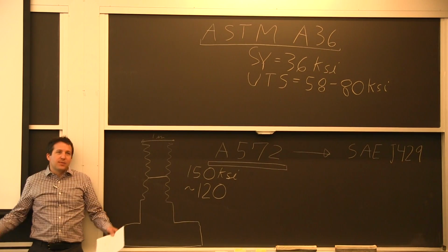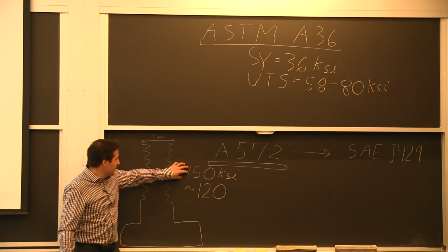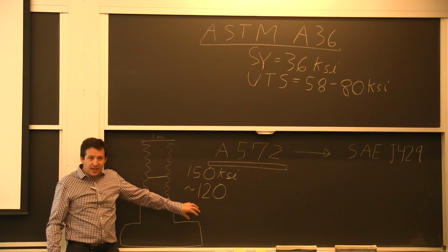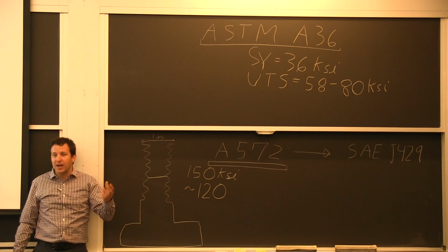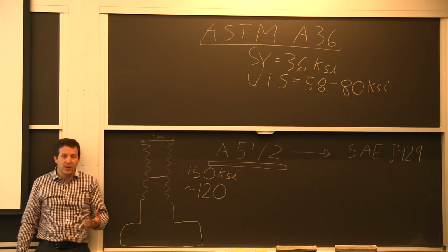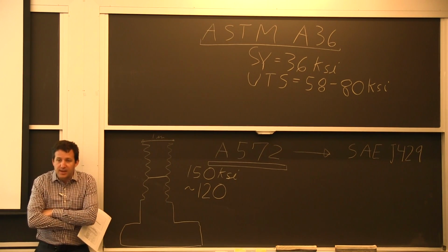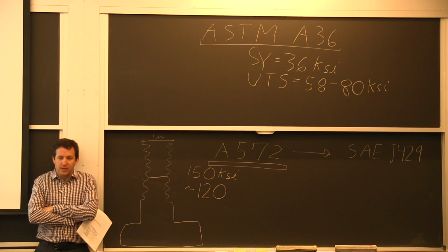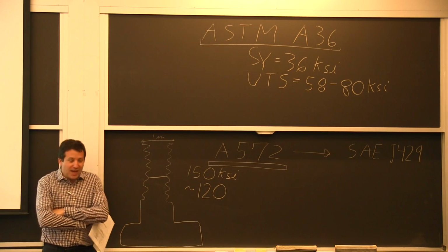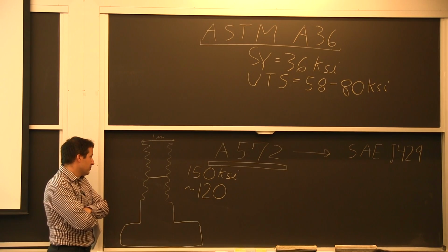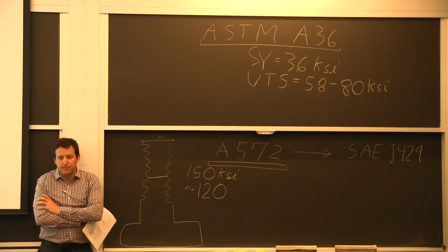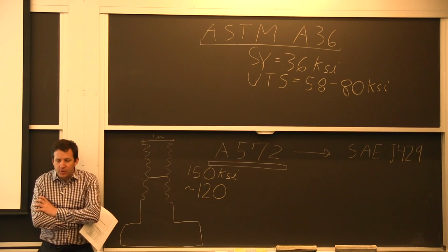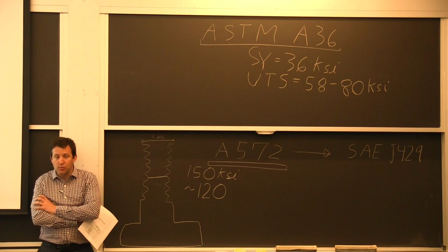Now, if you reduce the yield strength, I said 150, if you reduce it, it will reduce that 28 KSI to 18 or 13 or whatever it is. So you still care about the initial yield strength, because that's what prevents you from initiating cracks, if you have seen that part of material strength. But you're not getting exactly what you could think you're getting when you're looking at these tables. One way to avoid this issue is to preload the bolts.